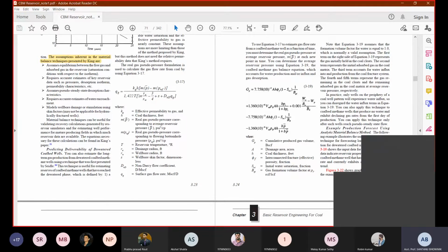So then what will happen? The water will not be able to move and it will give pressure. So obviously the pore pressure is going to change, and this change in pore pressure is going to significantly change the effective stress consideration, which will destabilize your reservoir characteristics from the mechanical point of view. Okay, so this type of thing you need to consider for the water area.